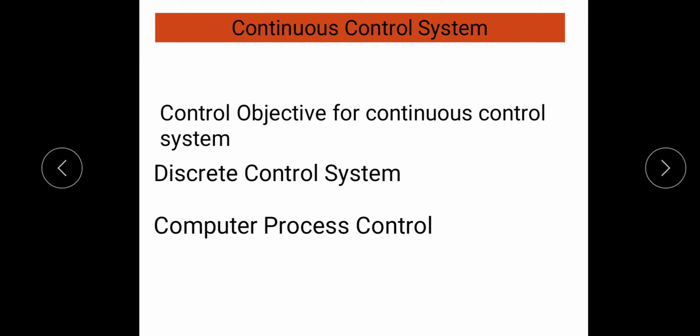The disadvantage is the reliance upon the measurement of variables in the mid-process, which may not be 100% accurate, thus affecting final output variables. Feedforward control is combined with feedback control in many models to overcome the problems.